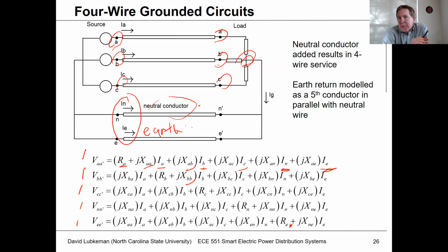One thing we're going to be assuming when we do this calculation for our overhead models, and this is very common, is that when we get to these endpoints, we have an ideal grounding connection to Earth, right? So normally we are going to drive stakes into the ground. Normally there'd be a little bit of resistance in here, but we're going to ignore that. We're going to assume that this is kind of an ideal connection here, and that's going to simplify our math.